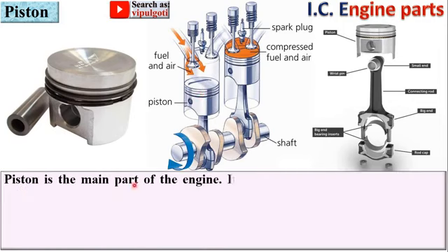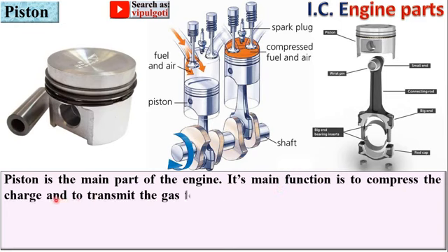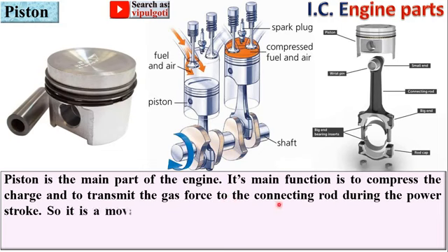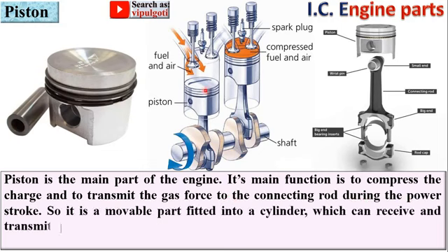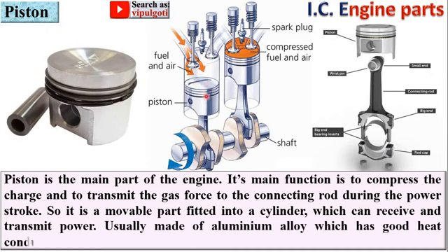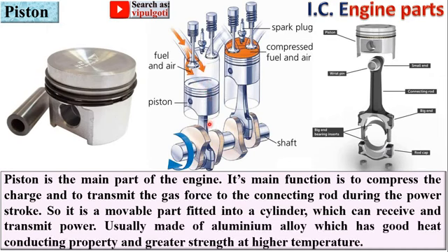Piston is the main part of the engine, its main function is to compress the charge and to transmit the gas force to the connecting rod during the power stroke. So here you can see whatever the gas force that is exerted on the piston, that will be transmitted to the connecting rod during the power stroke.